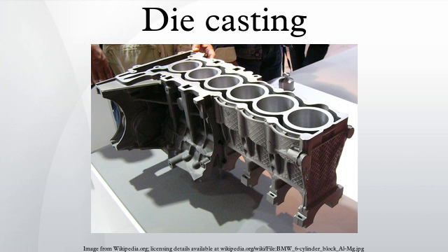The dies used in die casting are usually made out of hardened tool steels, because cast iron cannot withstand the high pressures involved. Therefore the dies are very expensive, resulting in high startup costs. Metals that are cast at higher temperatures require dies made from higher alloy steels.